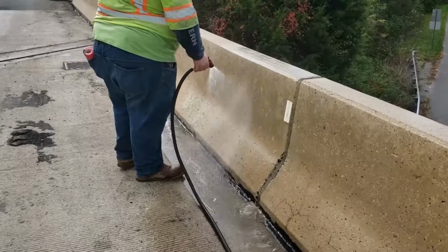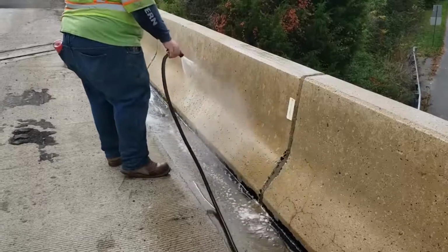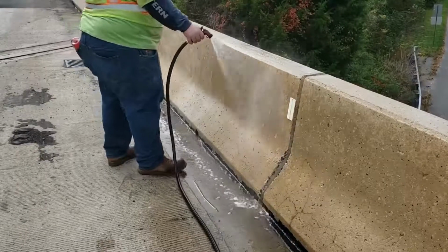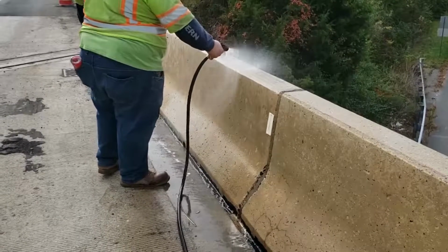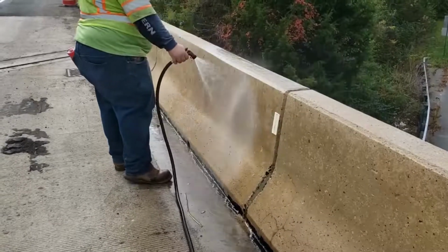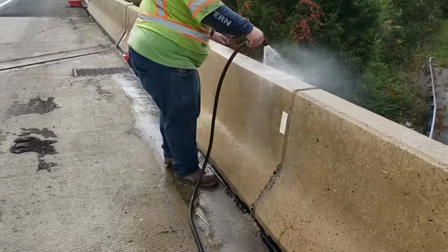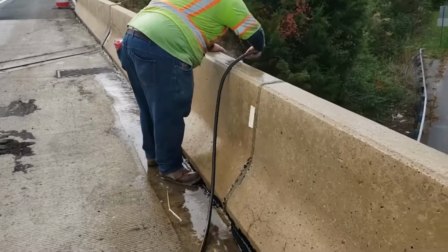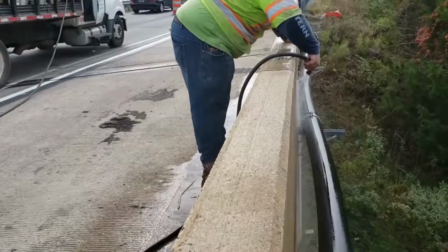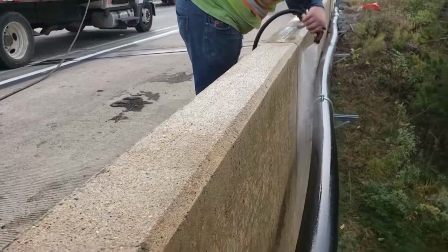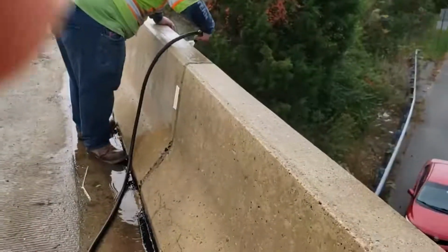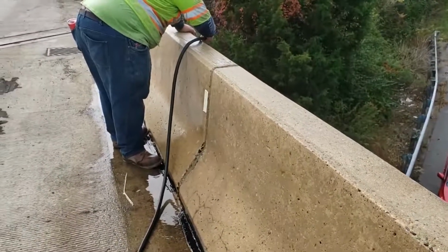They're applying water. This technology can be applied on vertical and horizontal surfaces. In this case, Delaware DOT, they are applying to Jersey barriers. So on the vertical, the material is going to penetrate through diffusion. So it doesn't matter if it's horizontal, vertical, or if it's upside down, the material is going to penetrate the structure, the concrete. And here you see the watering phase. So they water to activate the materials inside the structure.